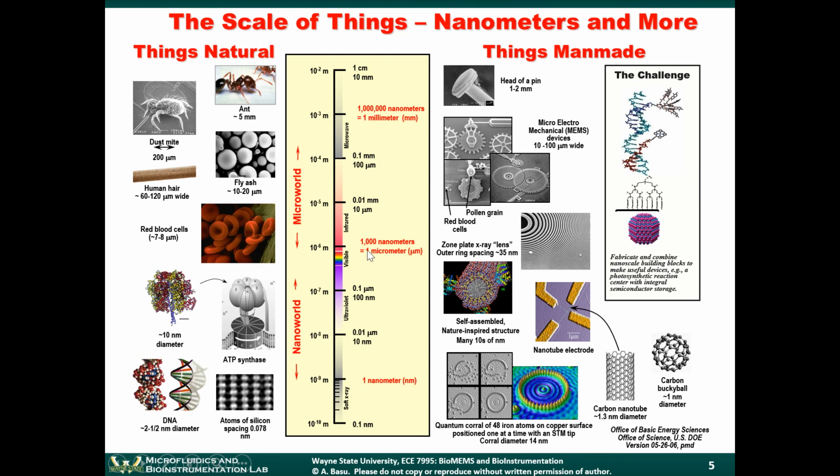Moving down to the nanoscale, using special lithography techniques like interference lithography, we can get the dimensions much smaller, down to about 30 nanometers, tens of nanometers. If we want to get devices that are 1 to 2 nanometers, we can use carbon nanotubes, which I just mentioned. If you can look at this graph here, this is an example of a nanotube electrode. The gold-looking regions here are patterns of gold. The dimensions here are a few micrometers.